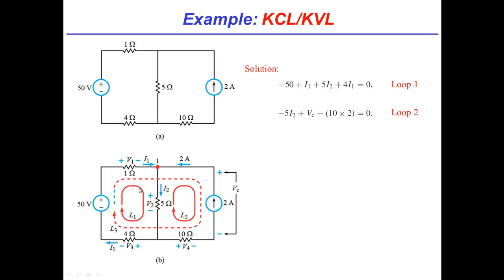Now, notice I did 2 steps here. This is just to get all of you to go a little quicker. In my head, I already knew that the voltage across this resistor by Ohm's law is the current times the resistance value. And notice, in all cases, and it wasn't by accident that we drew it this way, the current I1 is coming into the plus of the resistor, so it follows the passive sign convention. So all I'm doing is basically multiplying I1 times this resistance to get V1, right? I've made it match every time. The I1 points into the plus, the I2 here, sorry, and I1 points into this plus. It makes life easy.